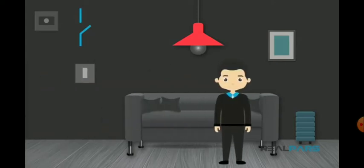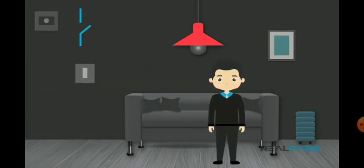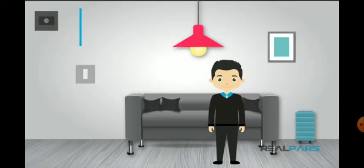Now, let's say that instead of the wall switch, I'll install a sensor in that room. This sensor has a simple open contact within it, just like a normal switch. The way that this sensor works is that it always looks into the room, and when it sees someone entering the room, the open contact is going to be closed, and following that, the light's going to turn on automatically.